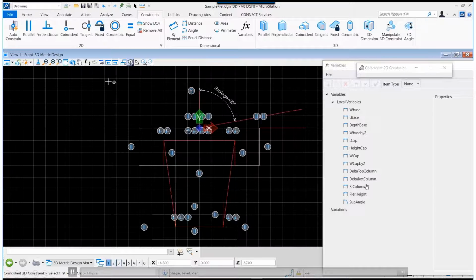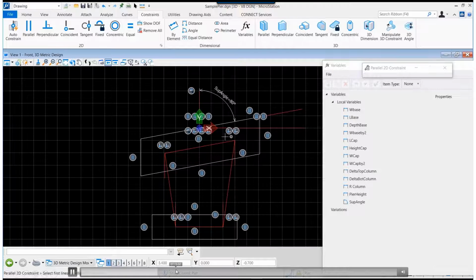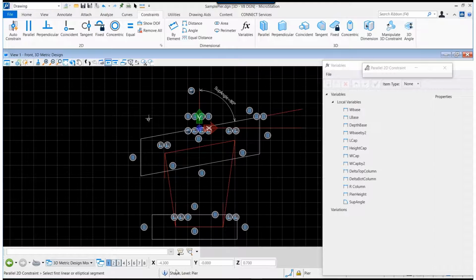Now after you keep placing these, later you will see that you will start changing dimensions, and then you can double check the variables that you enter, to see how it's moving parallel. So check whether the variables that you enter and their constraints are behaving the way you planned. If not, you have to delete each one of the markers and reconstrain it again, right?